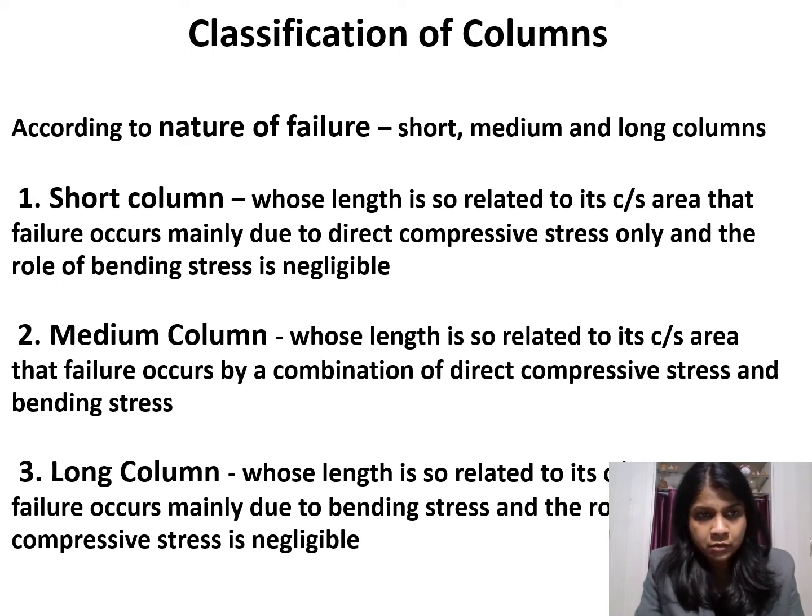Similarly, on the same ground, when will it be called a long column? Imagine there is a long column. When we apply some external load to the column, then what will happen? The column will try to buckle, to bend or deflect from its original position, and due to that bending, the bending stress will develop inside the column before the development of the compressive stress. So in that case, the column will fail due to bending only.